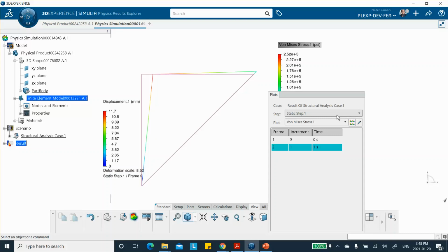Now, von Mises stress for a bar makes sense. For a link, it makes sense because it doesn't matter at what cross section you look at. But when you have a frame element and it's bending, then the von Mises stress is not a single value along the bar. It depends on what location on the frame, what cross section, you're looking at. And that's it. Have fun.